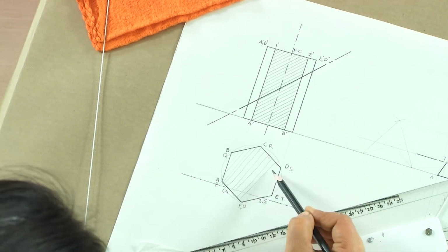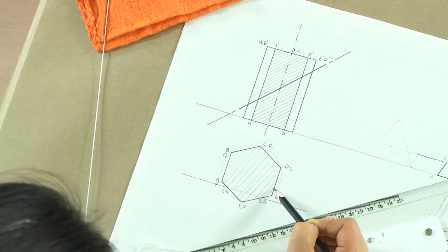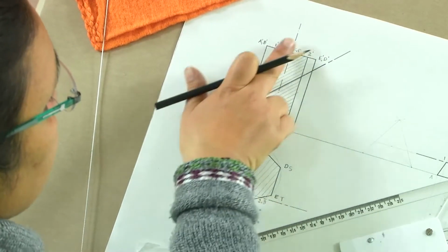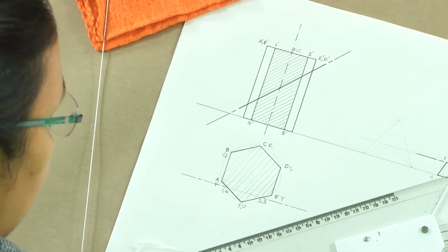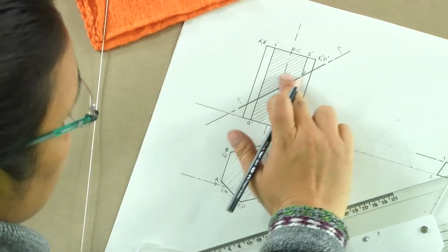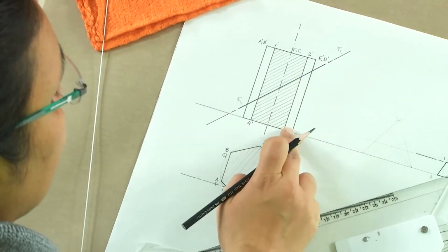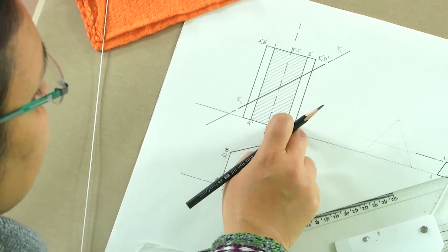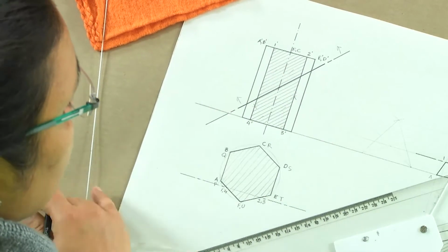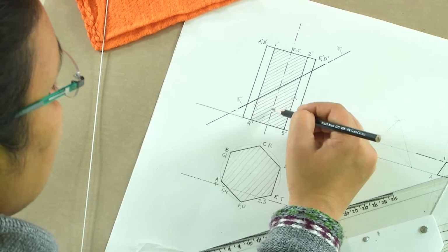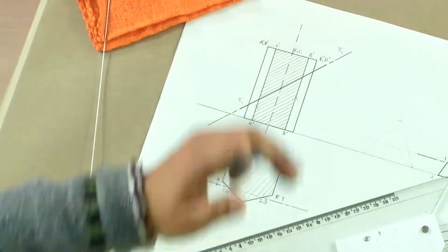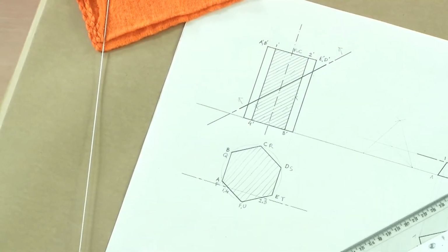So this is going to be the top view of the prism. The remaining portion on the top of this section plane to this side is going to be taken off. So this will all become light, and we will only darken the portion which is below. These two lines are not there, the sectional hatch is not going to be there, and we will only be seeing the edges intact, and there will be a section line assuming the top portion is cut.